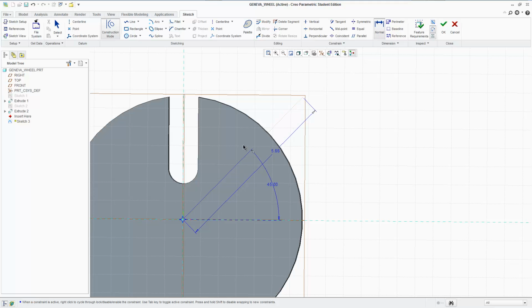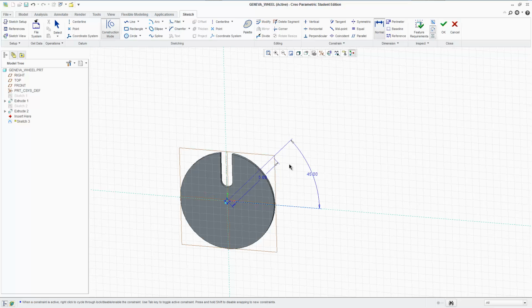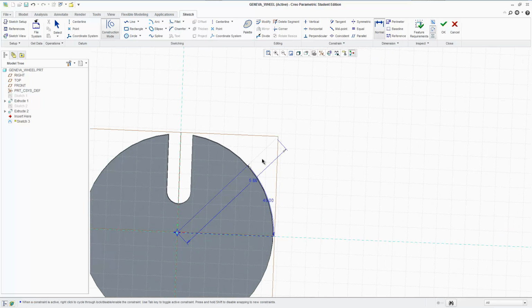It's going to make sense once I actually make the whole thing, don't worry. So again, to change the dimensions of anything, not necessarily just construction geometry, you click on normal, select the line, middle mouse button click, and if you want to change the dimensions of something in reference to another thing, you activate this tool again, hold down control, select the two things you want to control, and then middle mouse button click. And then you can control almost anything and be precise with your creations.